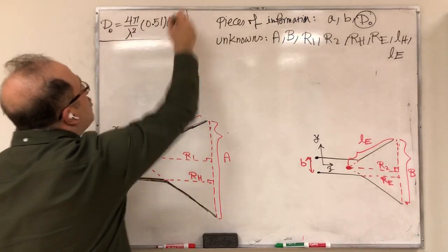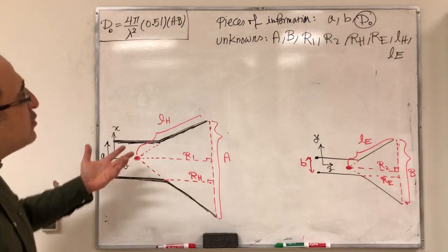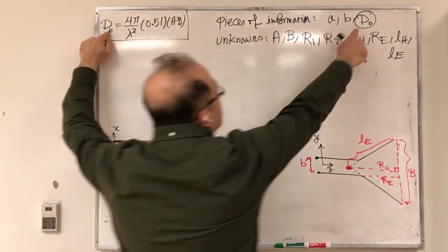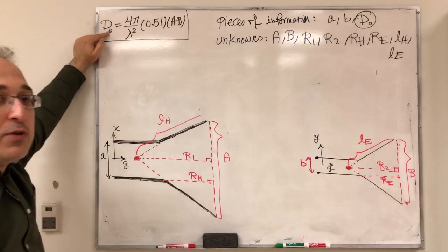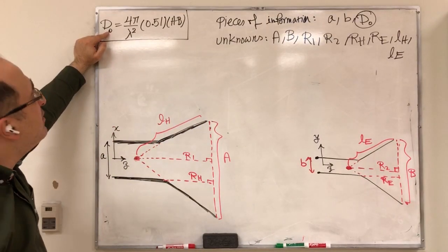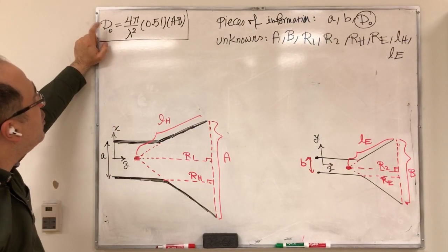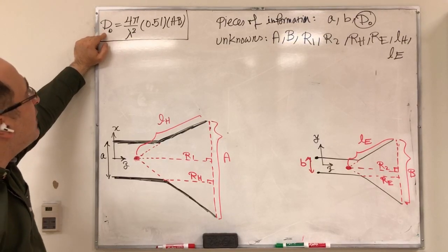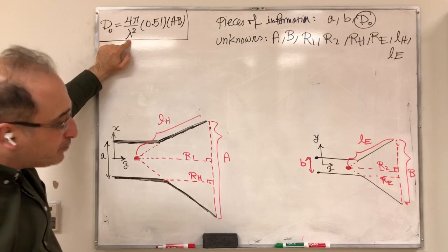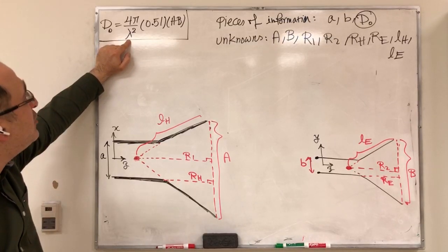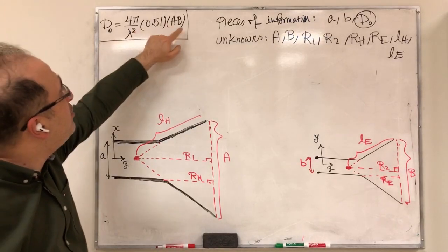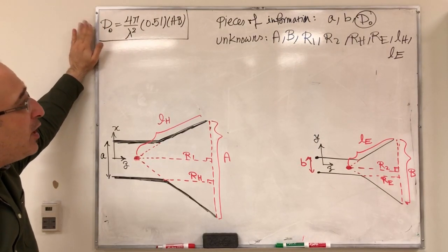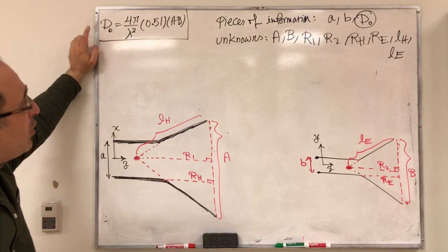Now look at this equation. This equation is actually very helpful because it connects one piece of information. Let's say someone wants to have a 10 dB directivity, for example, so you know your directivity is 100, dimensionless, and then you know your lambda, which is the frequency at which you're doing design, then AB is connected to the known piece of information. So that's one equation right here.